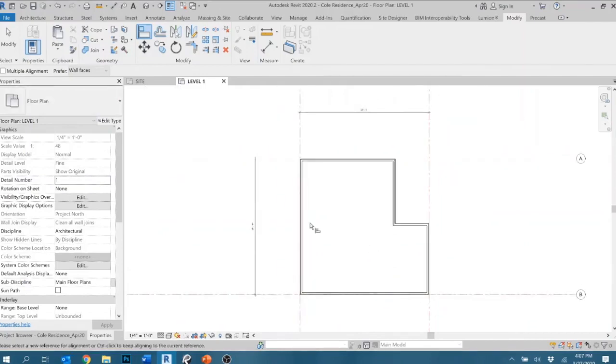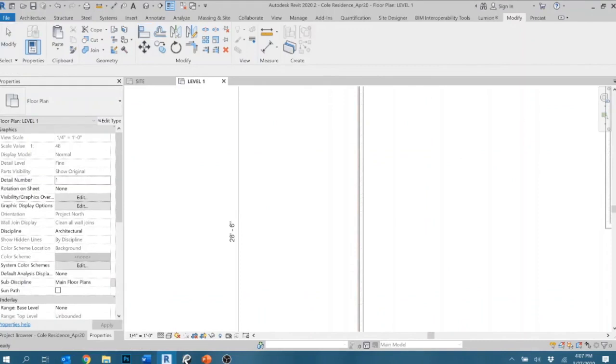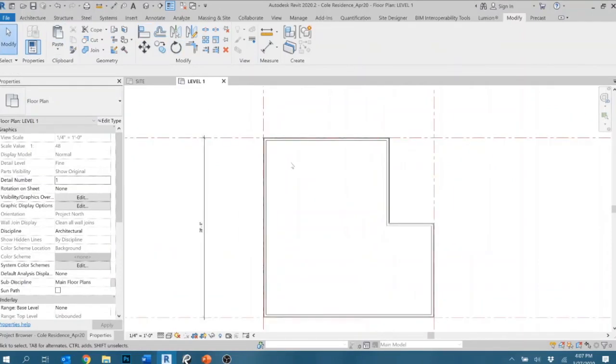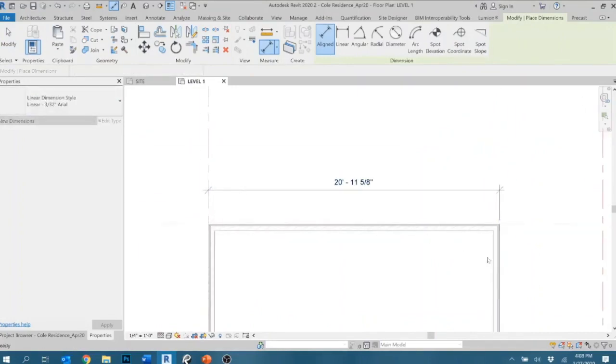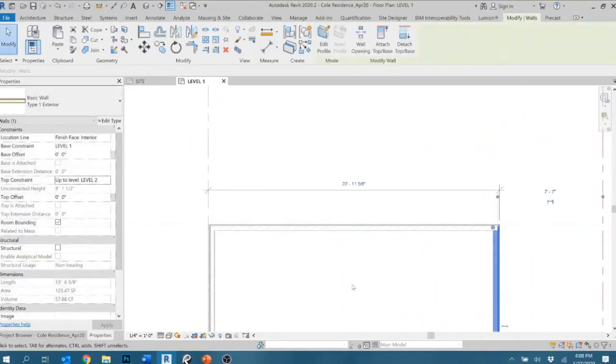Okay, so I know the 28'6" is correct. I'm just going to then go around my entire wall perimeter, making the adjustments. The next one I dimensioned at 24'4", so I'll use my dimensions string to ask myself what it is. It's not quite there. I touch the wall I want to move, touch the dimension, and type in 24'4".